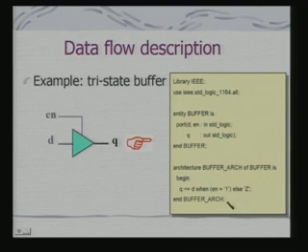Okay. So, if you look at when, it means why it is a data flow model, because it tells you that when enable, if you consider when in a literal sense, it is associated with the concept of time. When this signal becomes 1, then only that Q, okay, should be representing D, otherwise it would be Z. So, it is a data flow model, it is not just a behavioral model.